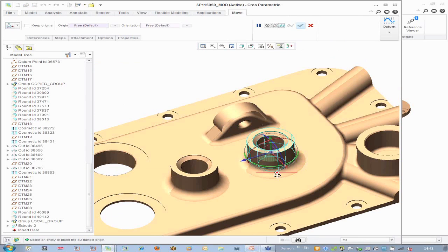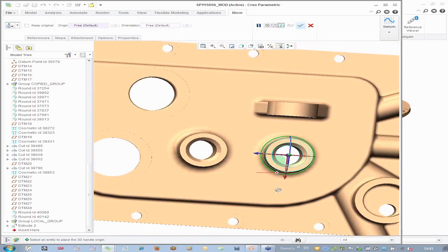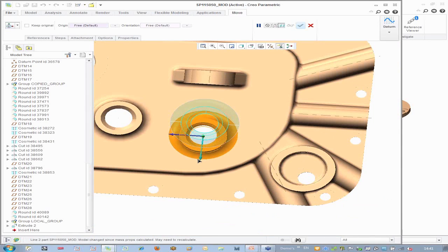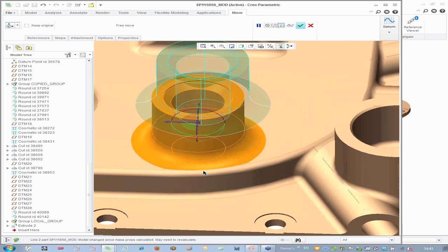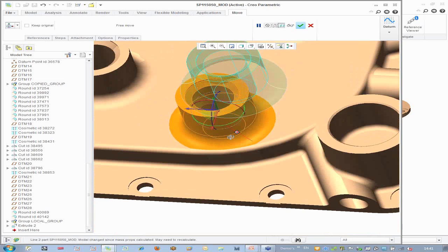So when I move it, it's not simply moving the geometry which you select. It's actually doing an awful lot of topology checks and changes. Because as we pull this to the side, you would expect that there'll be changes made to this round. And you'll notice there that the round is indeed changing. It's not just putting that geometry straight off the side of the surface. It's changing it as I see the thing get dragged.